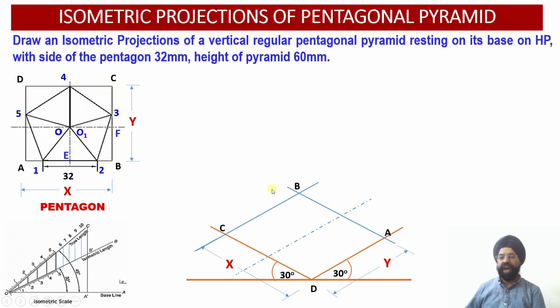Now I will be measuring the distance of point B with point F over here, and the isometric distance will be projected over here. Now the second center line will be drawn. With this construction, I have been able to work out, through rectilinear distance measurements, the center point or axis point of this particular base of the pentagonal pyramid.